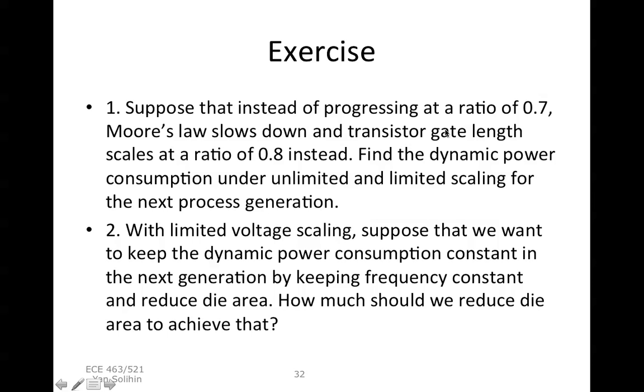Okay, and this problem is intricately linked with increasing the pipeline depth and pipeline width, because increasing pipeline depth doesn't improve performance much, but it increases power consumption by a lot. Increasing pipeline width quadratically increases the complexity of the die, which means quadratically increasing the power consumption. So therefore, because we have a power wall, those things have to be abandoned.